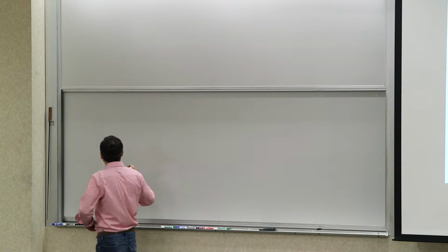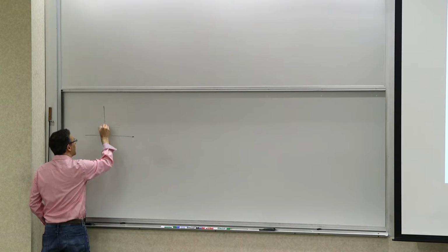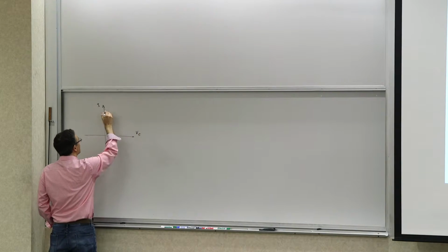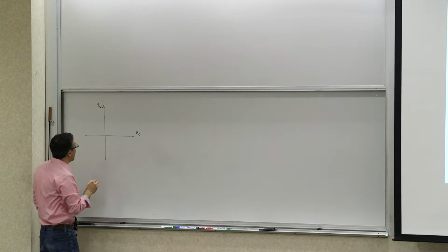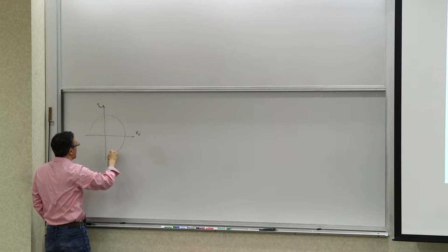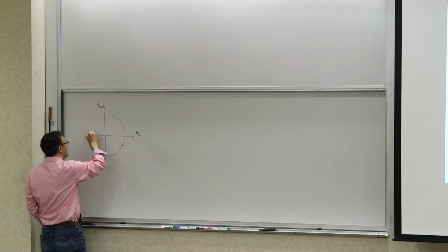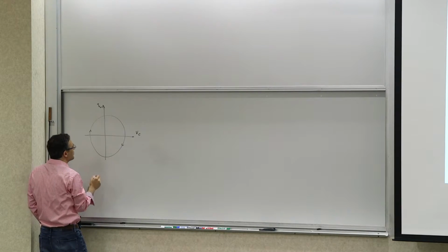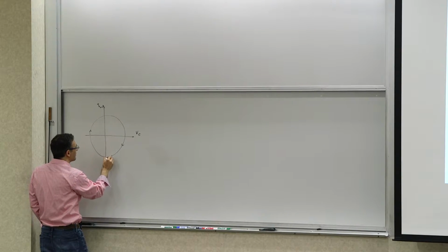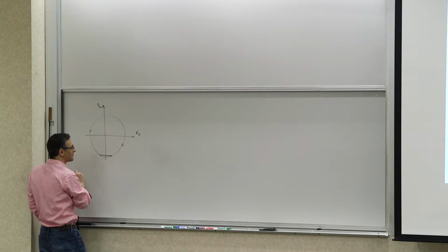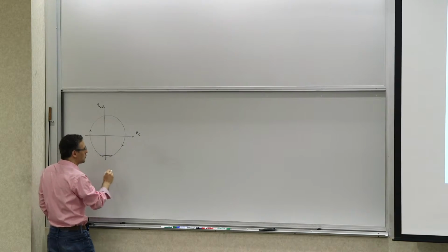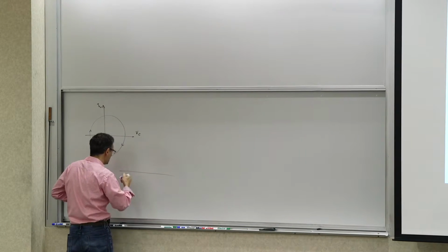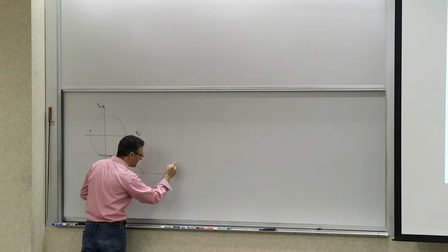So let's think about that point. You can also view the oscillator in the state space. For example, if you have an LC, you can look at the V of the capacitor and the current of the inductor, and the oscillator is going through a closed trajectory in the state space. So when you inject an oscillator with an impulse, let's say here, and you push it here, let's say this was the original waveform of the oscillator.